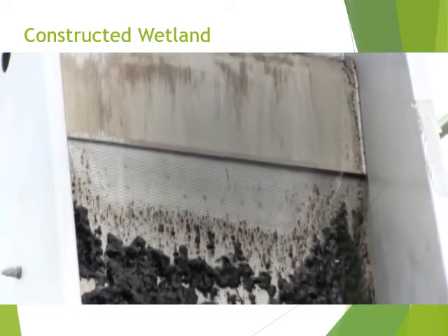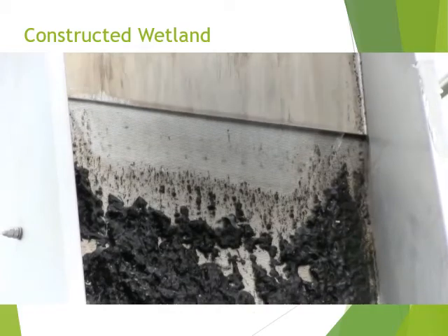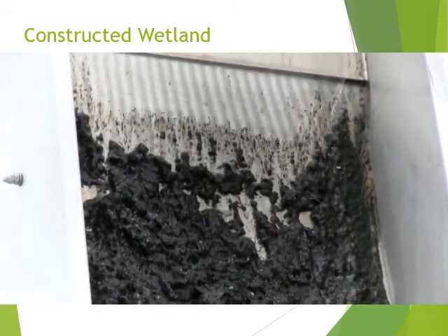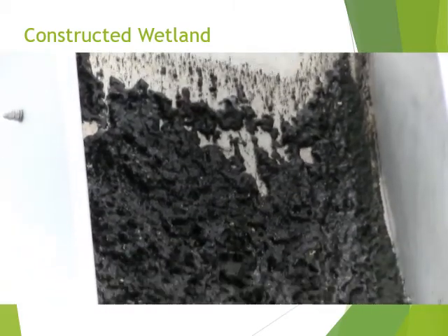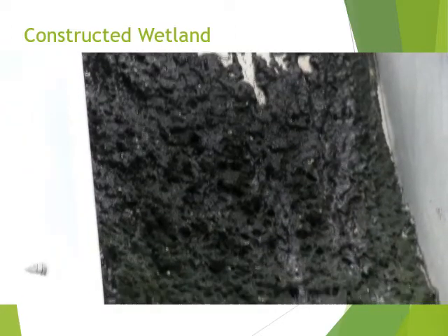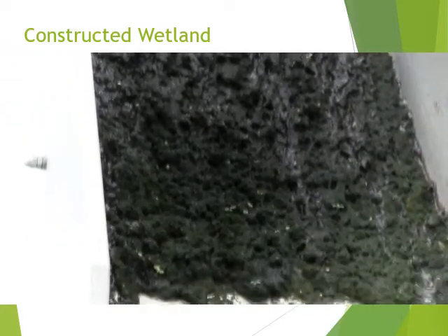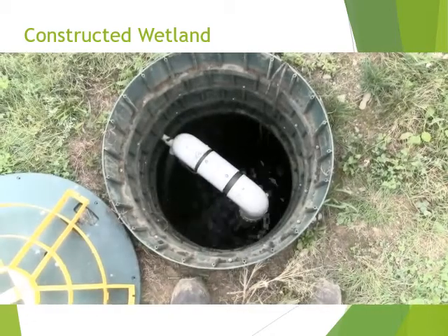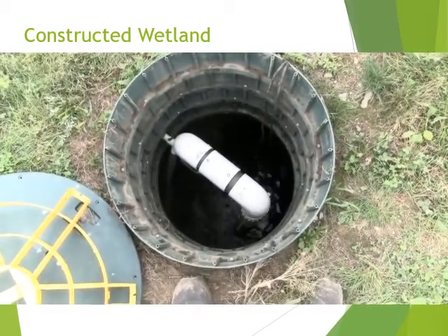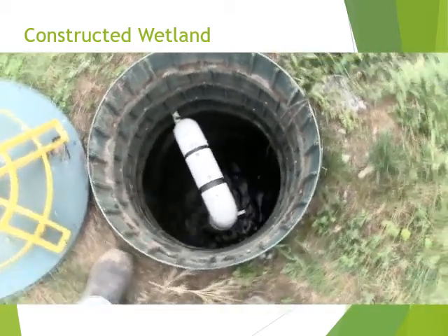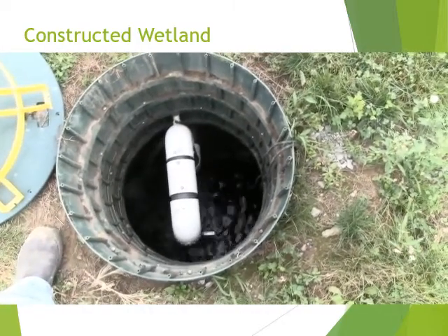As the water moves down over the filter, the peat moss is separated from the water stream. This peat moss ends up into a bin, and the water ends up and is treated a little bit further via cloth filter in the next step. So water from the coarse screen filter enters this pump tank. This pump tank then applies the water to cell 1 of the 3-cell constructed wetland.